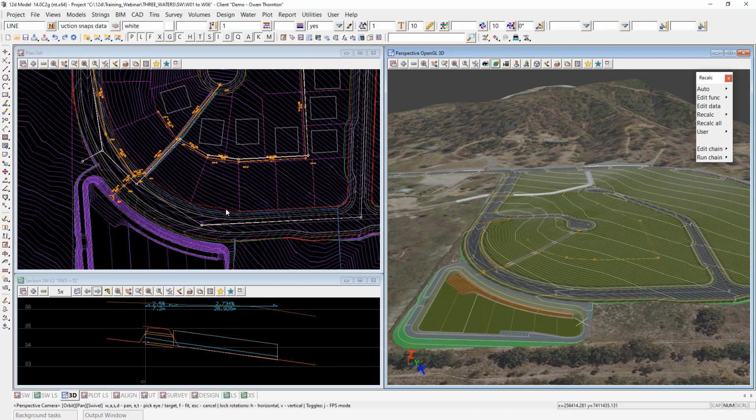What I would tend to do is use your reference string in the road design file for getting the chainage and offsets of your nodes, because that's what defines the chainage, the reference string. Once you've established that in your road design file, you could probably set all of the road chainage modes to manual, so it won't try and recalculate that again,